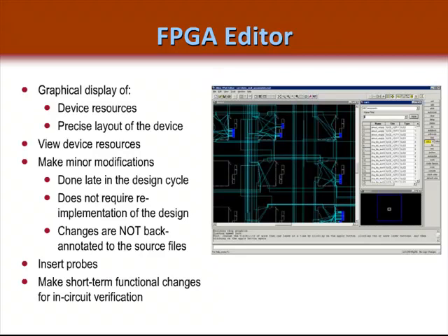Don't forget that any changes you make to your design with the FPGA Editor are not reflected to your HDL source code, which can be dangerous, so any changes should also be made to the source HDL. This utility is probably best used for adding probes and making short-term functional changes for in-circuit verification.